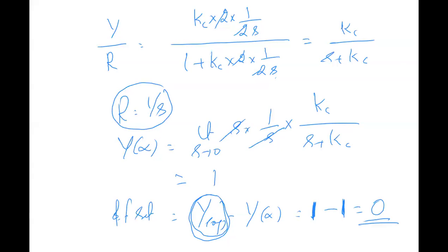But if you intentionally change the set point from 60 to 70, the temperature of the CSTR should also become 70. Why have you made it 70? Because you want to operate the reactor at 70. So when you change the set point by 1 unit, you are expecting the response also to change by 1 unit. Clear?